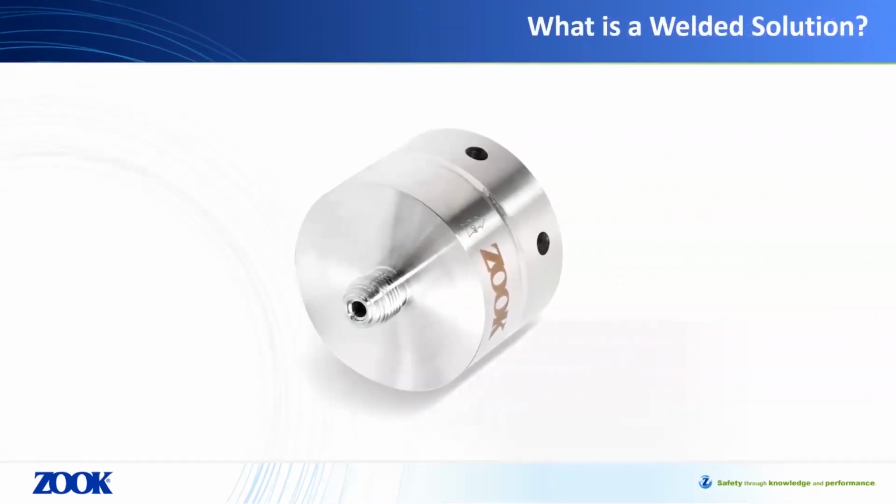So what is a welded solution? A welded solution is really a methodology of installing a rupture disc within an application or system that utilizes various welding processes to weld the disc between one or two machined components. The design and welding method of joining the components is dependent on the specific application.